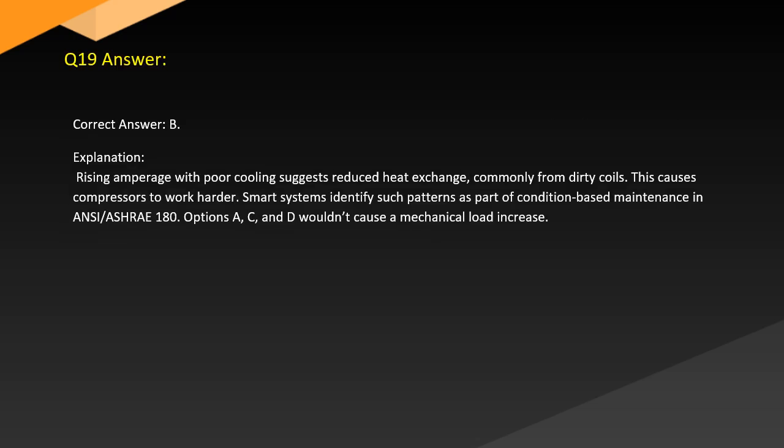Answer. Correct answer: B. Explanation: Rising amperage with poor cooling suggests reduced heat exchange, commonly from dirty coils. This causes compressors to work harder. Smart systems identify such patterns as part of condition-based maintenance in ANSI 180. Options A, C, and D wouldn't cause mechanical load increase.